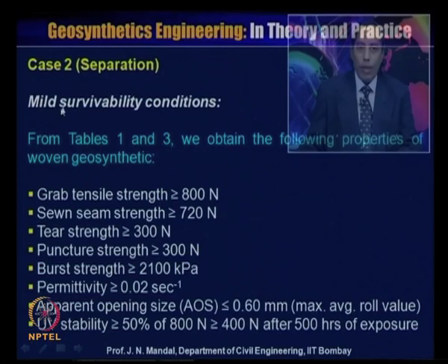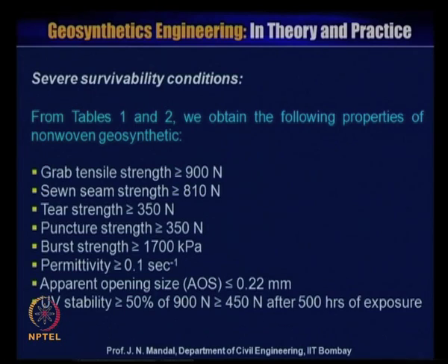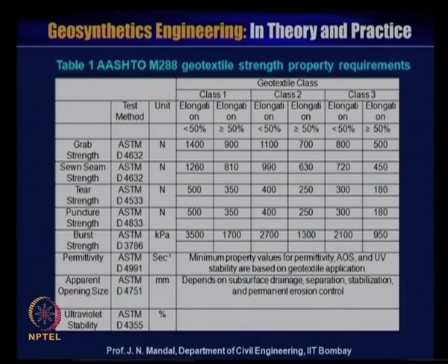Because this is a mild severity condition, remember, mild severity condition. So, Grab strength you can see from table 1 and 3, because it is the mild. So, this will be class 3, and it is also less than 5, that is why we have taken this value.